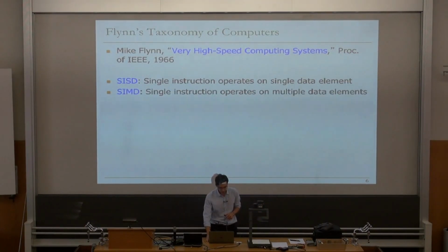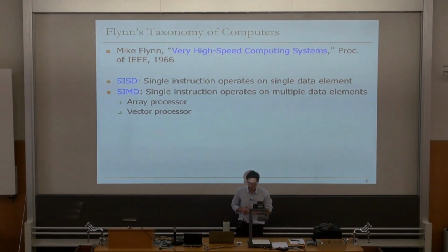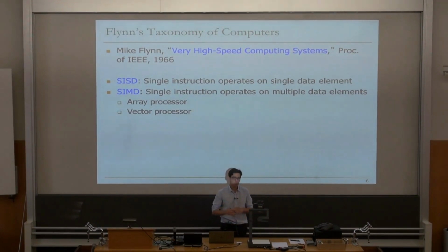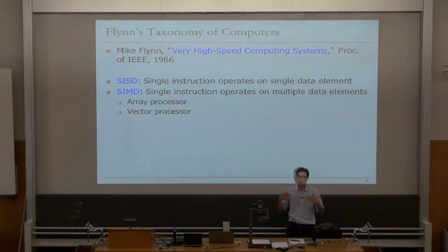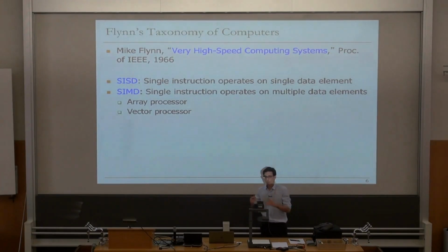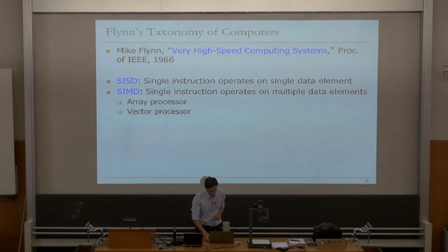The second category is single instruction, multiple data. And this is what we are going to talk about today, including array processors and vector processors. And here, the thing is that we have one single instruction, and because the workload that we are going to operate on has inherent regular data parallelism, with one single instruction, we are going to be able to operate on many different data elements at the same time.